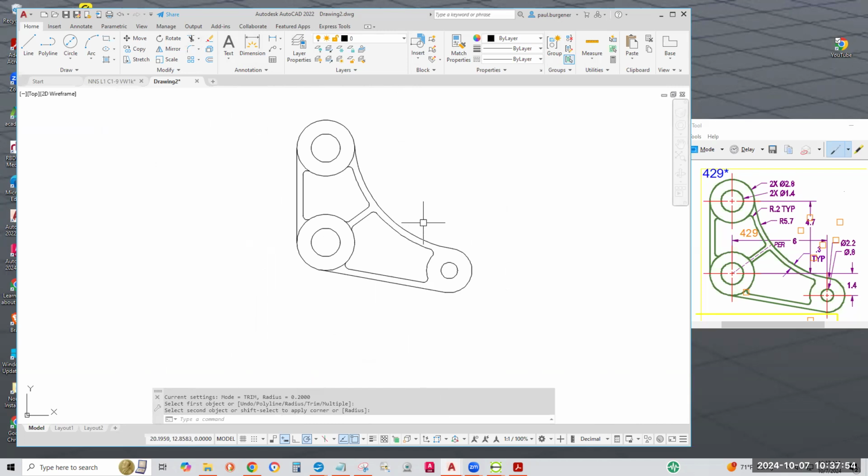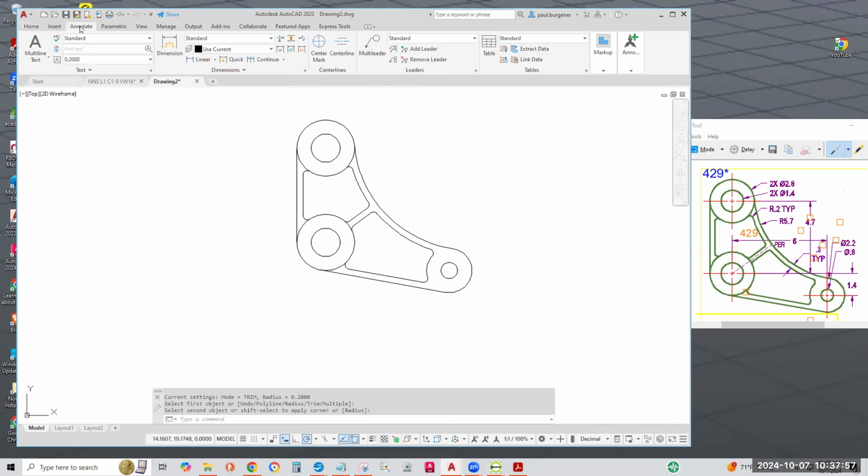Now for center marks, I've been teaching lately this new center mark icon, but it'll likely be on the current layer, it'll be a center line type, and so on. Anyway, there's lots of adjustments to make when you do center lines. There's two or three system variables where you can control the layer it's on and the line type it comes in on, which I recommend continuous.